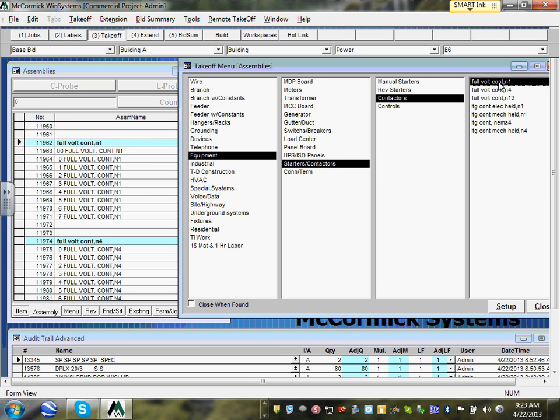The enclosure is the cheapest. NEMA 12 is the outdoor. So you're going to be at NEMA 1. The enclosure is NEMA 1, like this is an enclosure NEMA 1. Yeah, no. There's 2 NEMA numbers. One NEMA number for the enclosure and another NEMA number for the contactor size. The contactors go from 0 to 9. The NEMAs go from 1 to 12 or 14. I can't remember. And there's a bunch of others. 0, 0. You're right. It goes from 0, 0 to.